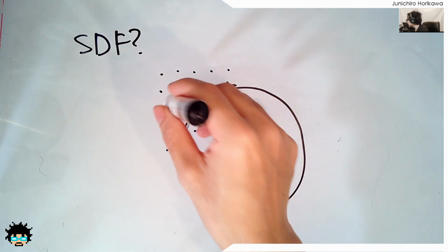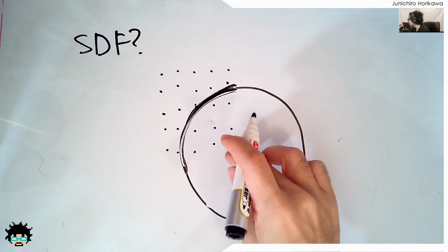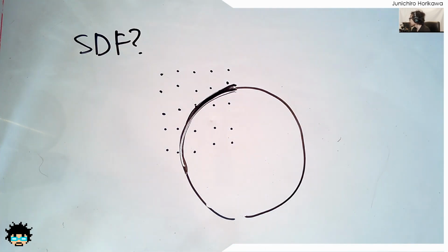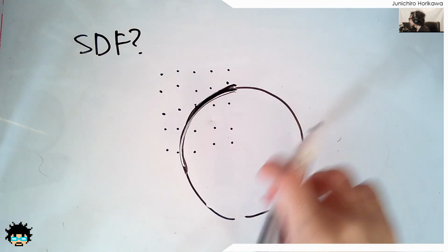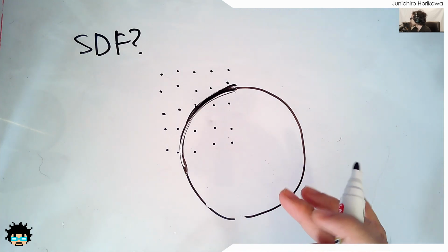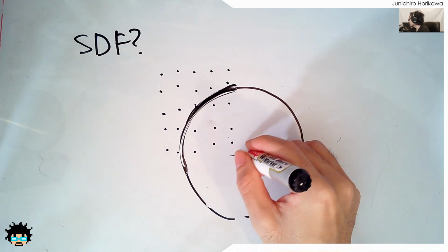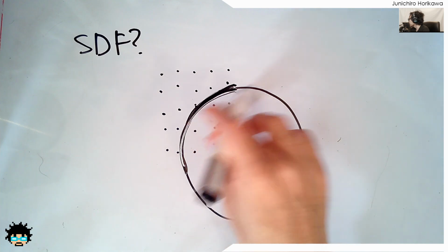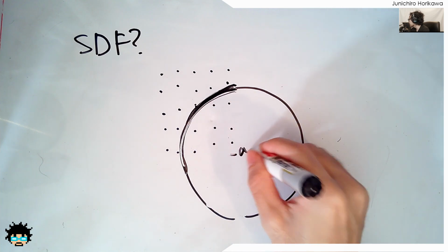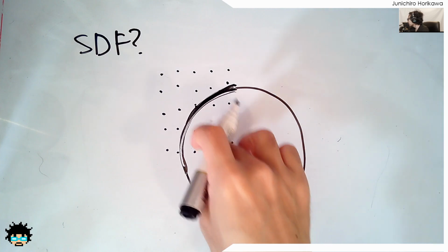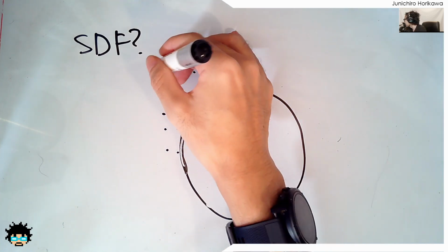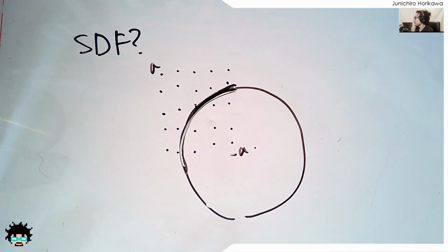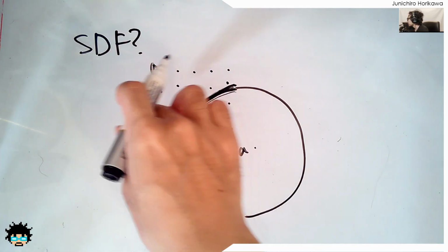Now, each voxel has its number applied, same as density, but the way it is being used is a bit different. If the voxel point position is inside the geometry that you want to show as a surface, then a negative value is applied to the voxel value. For the points which are outside the surface or the volume geometry, a positive value is used for those points.